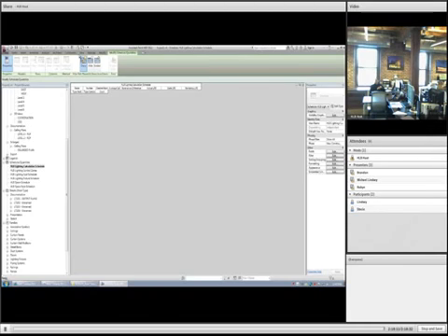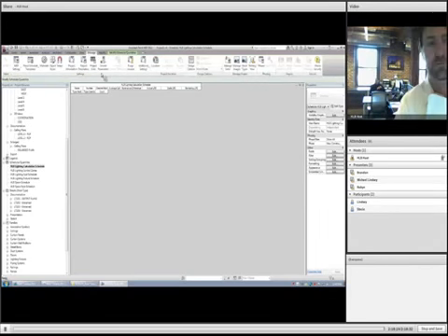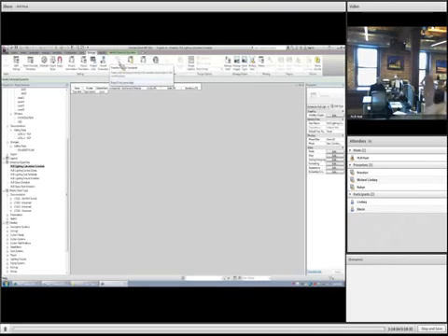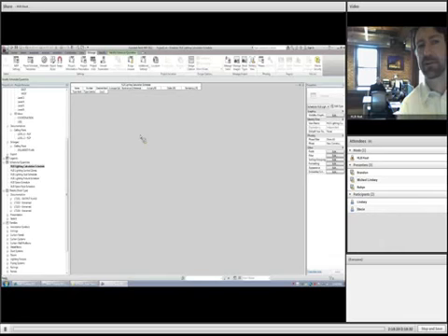All that's doing under the hood, and this is good from a management standpoint, IT standpoint too, is that at any point in time, if you have 2 projects open, say the template, and then a project file that may have been corrupted or bad, as long as you can get it open, you hit something called Transfer Project Standards, and you can take everything from